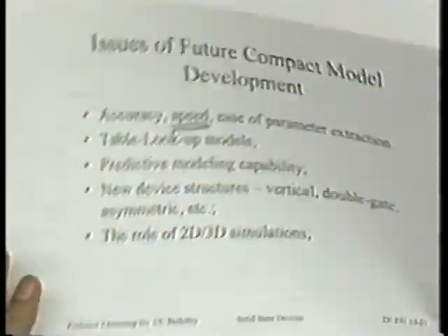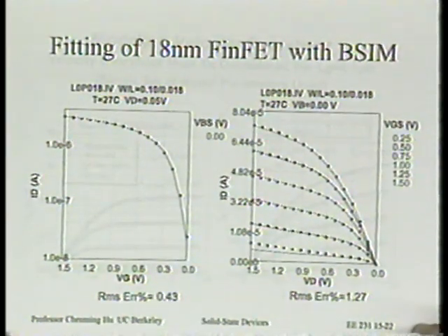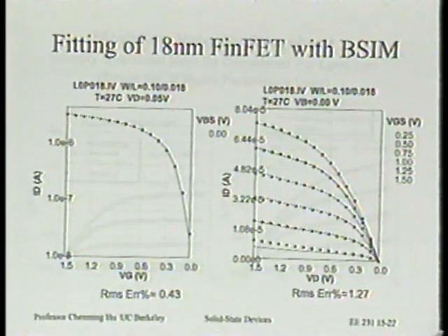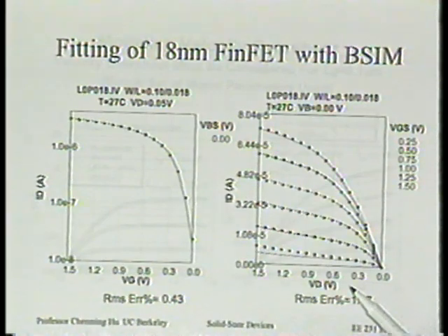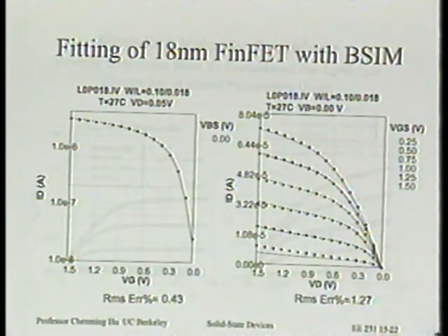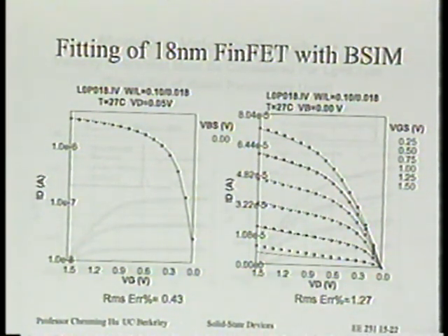So that is still far from what is needed. Now, as far as this second-to-last bullet about new transistor structure, I just happen to have this figure here. This is a 0.18 micron gate length, not electrical channel length. We don't know how short the channel length is, but the physical channel length is only 180 angstrom. This was a world record, done by students here in Berkeley. We call that FinFET. In fact, it's a vertical transistor. Its current does not flow in a planar way along the surface, but along vertical walls, and it's considered a very attractive potential new structure for the future.